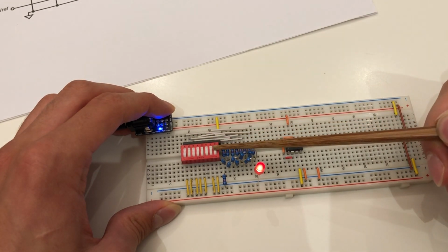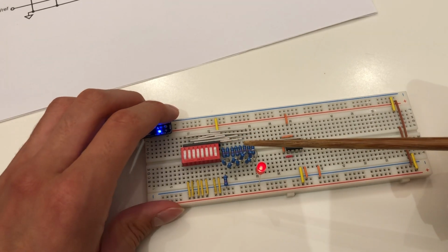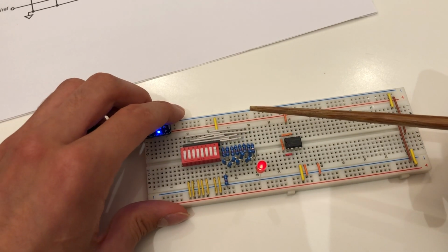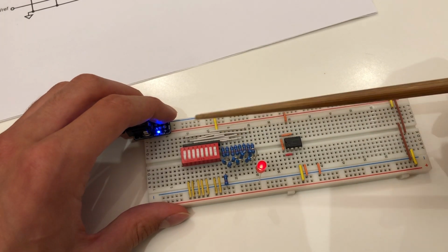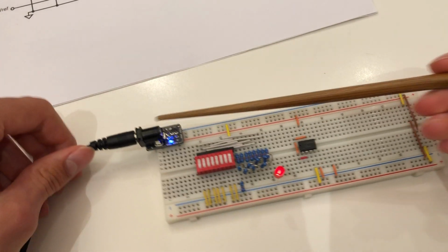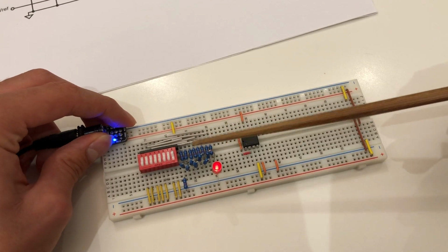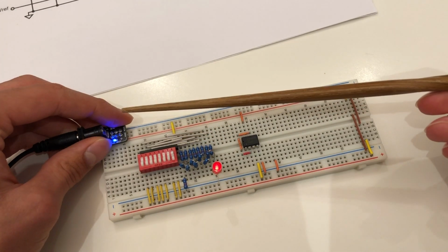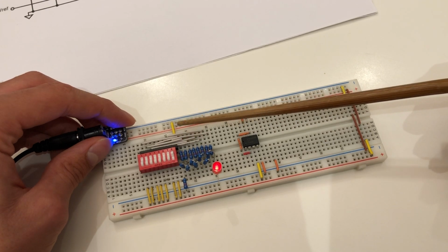Thevenin equivalent circuits and the superposition principle are used to break the R2R ladder down into simple elements and to calculate values respectively. Thevenin states that if you have a circuit consisting of linear components such as resistors and voltage sources, it can be simplified down to a single supplied resistor. Superposition principle says that any linear circuit with more than one power source can be analyzed by summing the currents and the voltage from each individual source.